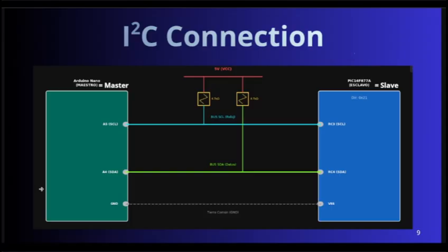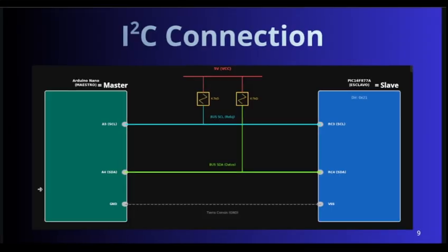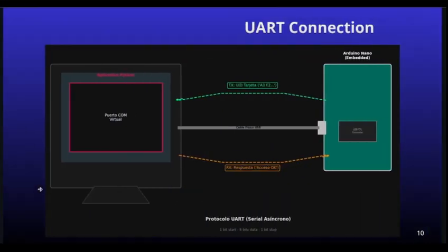In our case, the Arduino, as master, sends data frames containing the text to be displayed, and the PIC, as slave, listens at its address 0x21 and processes the data. It is the ideal solution for low to medium speed peripheral control on the same board.